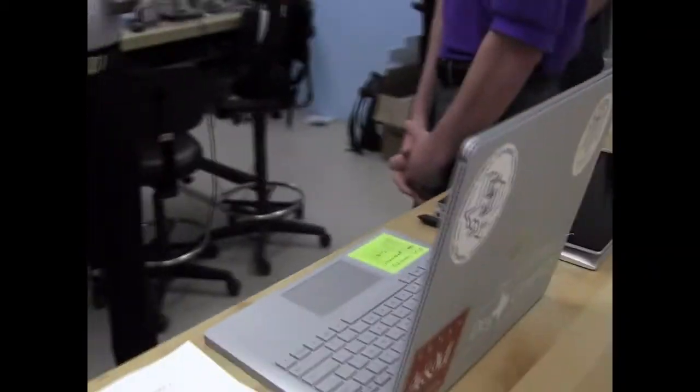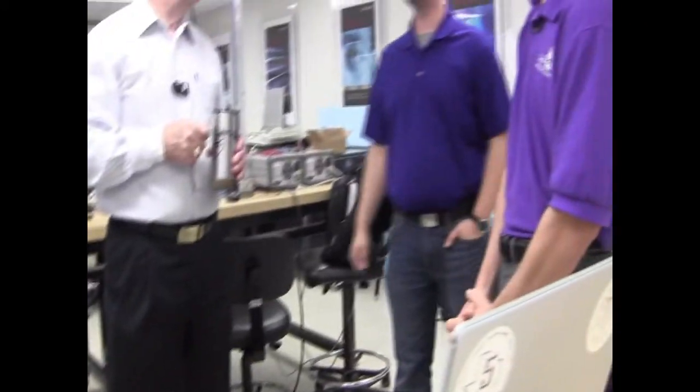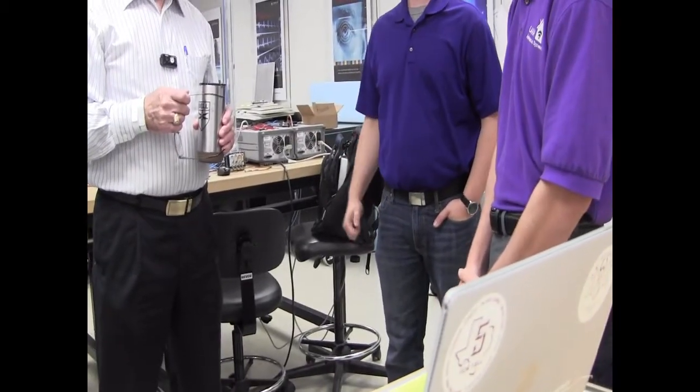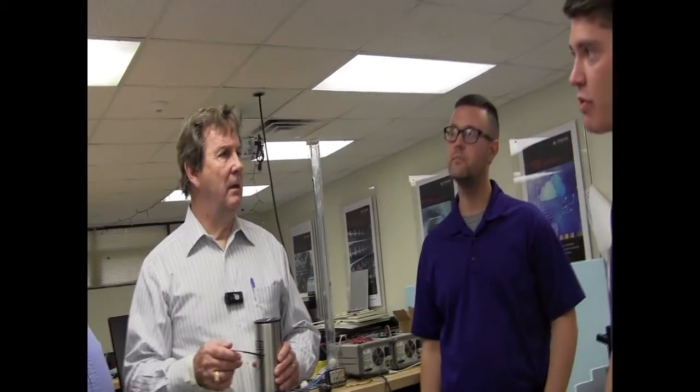It's saying the return air is 64 degrees, so the AC is going into protection mode because it's getting too cold. The temperature sensor isn't responding as quickly as the air coming right back out of the system. If y'all would like, we can wait for it to drop to 67. Otherwise, we've already tested it. Well, it's already at 69. I believe that about 4 minutes seems to work.